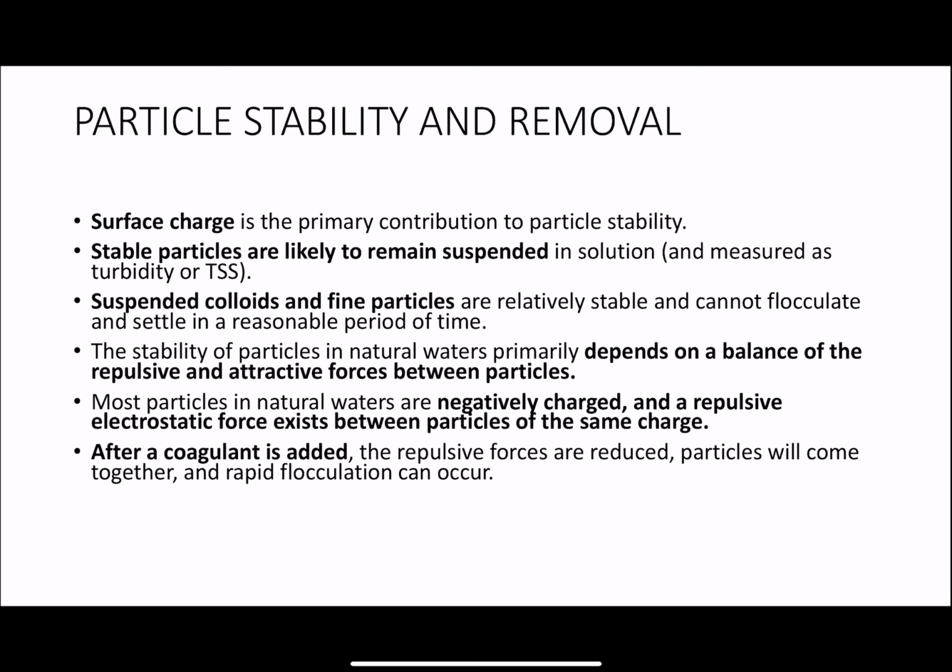Of course, these stable particles are likely to remain suspended in solution. And this is measured either as turbidity or total suspended solids. These suspended solids and fine particles are always stable and cannot flocculate, and cannot settle in a given time.